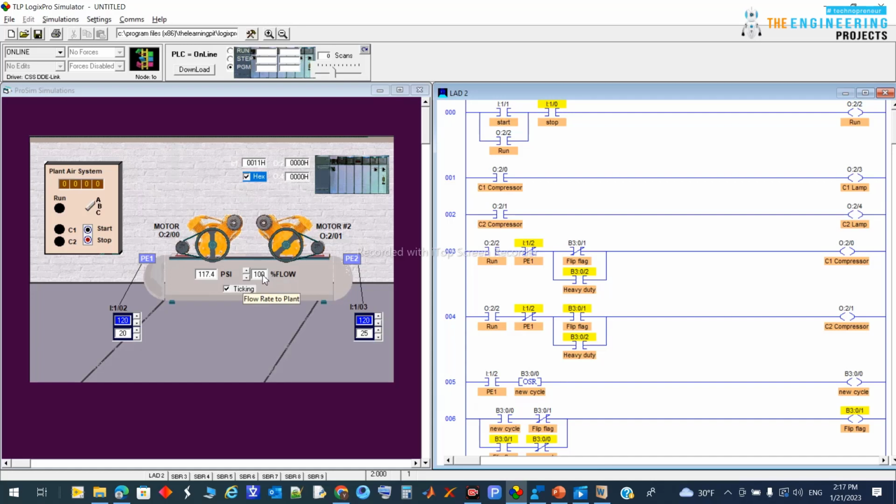So if the flow was open to a large value, at which the pressure pushed by this running compressor is not enough to increase the pressure, the cycle will continue forever, and this compressor will work for a very long time, and that's not convenient, because the compressor is now working under a risk of being damaged or not working. So let's first show you the condition.